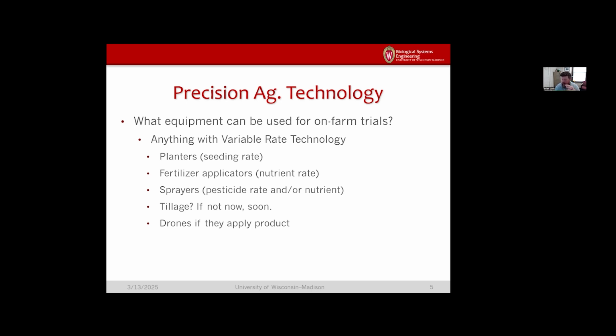It's an on-off valve, but we keep it open for a certain amount of time within a cycle, and we keep it shut the rest of the time. So a 30% duty cycle, say, would be, every second, it's open for a third, closed for two-thirds.